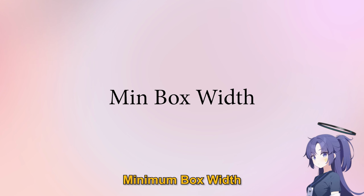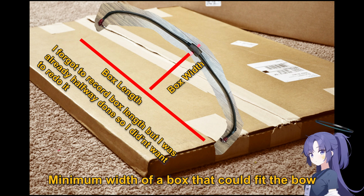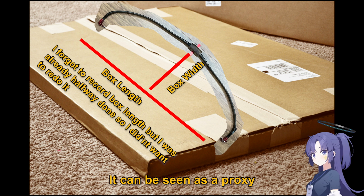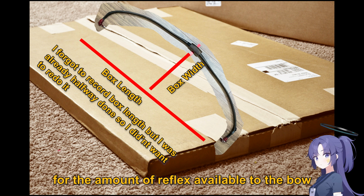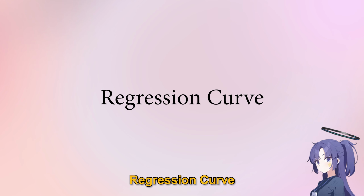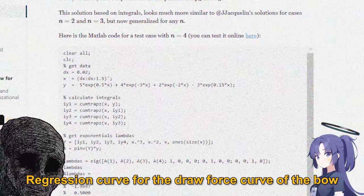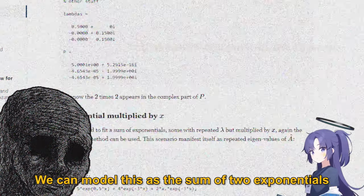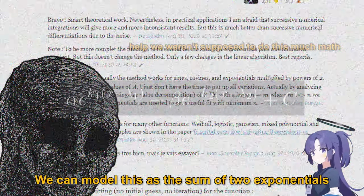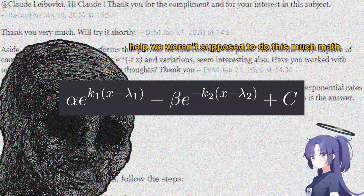Minimum box width. Minimum width of a box that could fit the bow. It can be seen as a proxy for the amount of reflex available to the bow. Regression curve. Regression curve for the draw force curve of the bow. We can model this as the sum of two exponentials. More details are available in the link below.